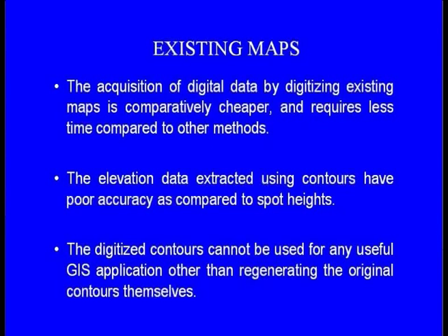The next is existing map. The acquisition of digital data by digitizing existing maps is comparatively cheaper and requires less time compared to other methods. The elevation data extracted using contours have poor accuracy as compared to spot heights.